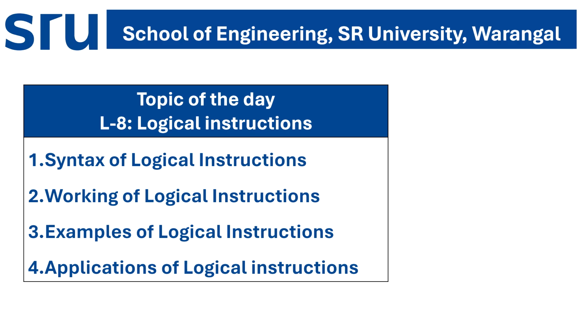First of all, the syntax of logical instructions. We will learn how instructions like ANL, that is the AND logic, ORL, that is the OR logic, XRL, that is the XOR logic, and CPL, that is the complement, which is for NOT logic, are written and used in programs, right?